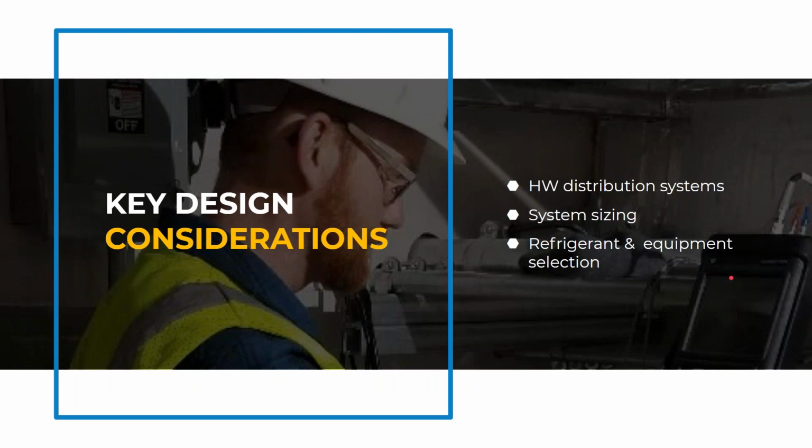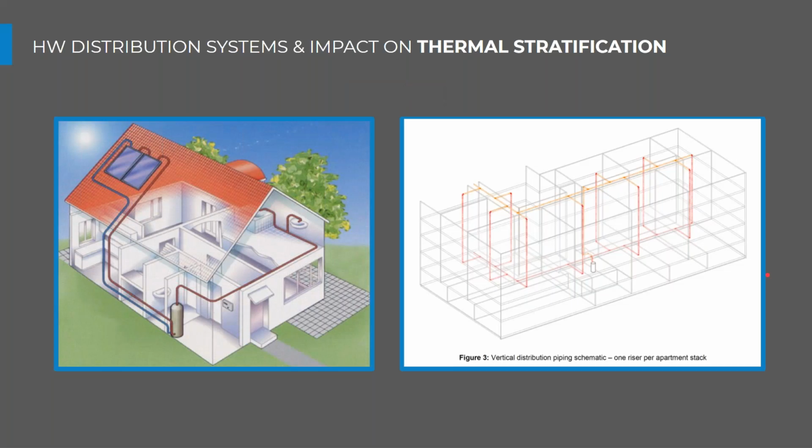So we understand a little bit about our efficiency boundaries, and we're going to touch on the hot water distribution system and how that impacts our system efficiencies. So the first thing to consider is how large, how dramatic, how great are those losses in your hot water distribution system. If we have high losses, we're going to need to be more conscious about them when specifying our temperature maintenance system and the equipment that's reheating that water.